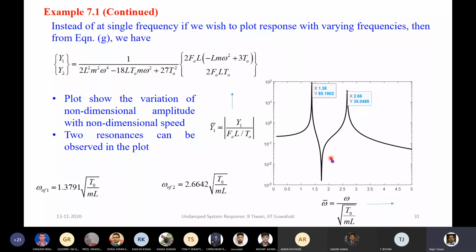So this is the typical plot of the force response. Because we have not considered damping here, the phase part is not plotted. Actually this is called a modal plot, in which we plot not only amplitude versus frequency, but also phase versus frequency.